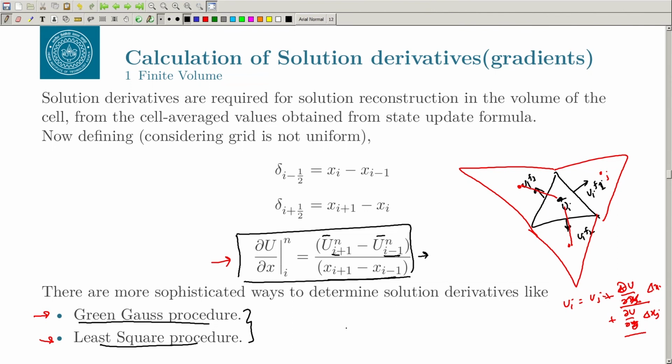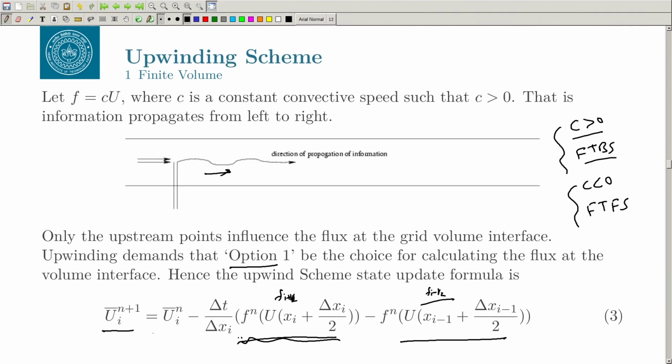So, ultimately you got all of the elements that you want. Delta t, delta x is fixed by your grid, delta t is based on the similar CFL criteria that we had for the finite difference. Same rules that we had, for example, if you want to use the explicit formulation, in most cases the CFL number is less than 1, the same kind of approach will work here also. And calculate the fluxes i+1/2 and i-1/2, update it and you can get the value.